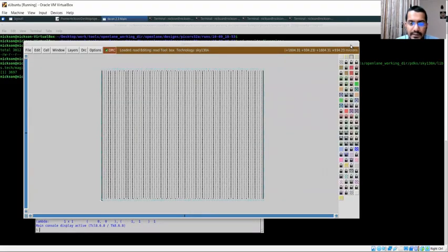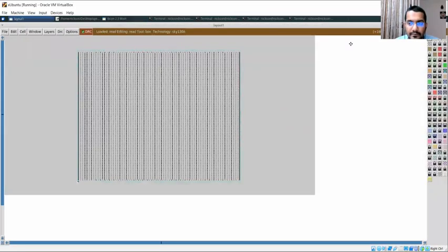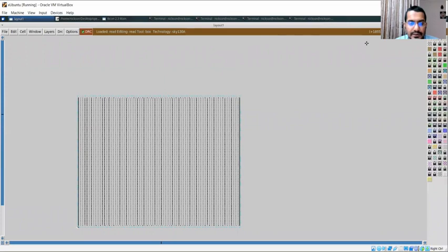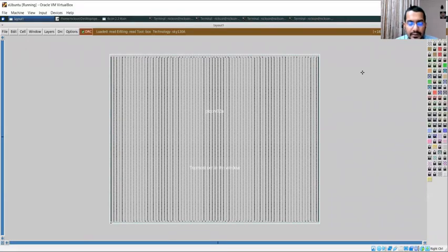So now there are a few things that I would like to draw your attention to. When you maximize this window, you can see your layout is somewhat not centrally aligned. So first of all, you need to select the entire layout and move it to the center of the display. So to select it, you press S on your keyboard. So you can see the entire layout getting highlighted, and then you press V. So that will fit this layout on your screen.